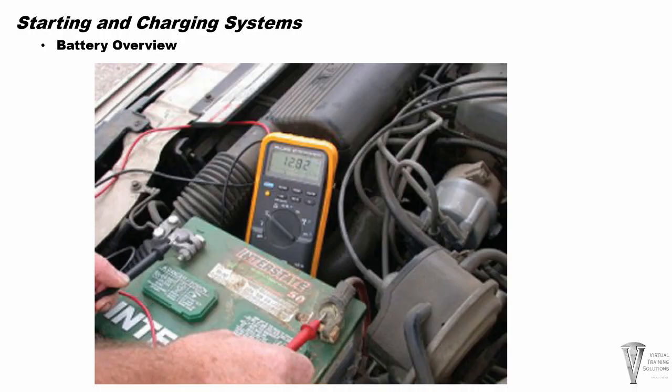A dead battery is the most common electrical symptom. Always test the battery thoroughly because a reliable battery is essential to the customer as well as the vehicle. Take the vehicle history and current usage into account. If a battery fails the tests, immediately recharge or replace as needed. If the battery tests marginal, immediately recommend a new one in writing if necessary.